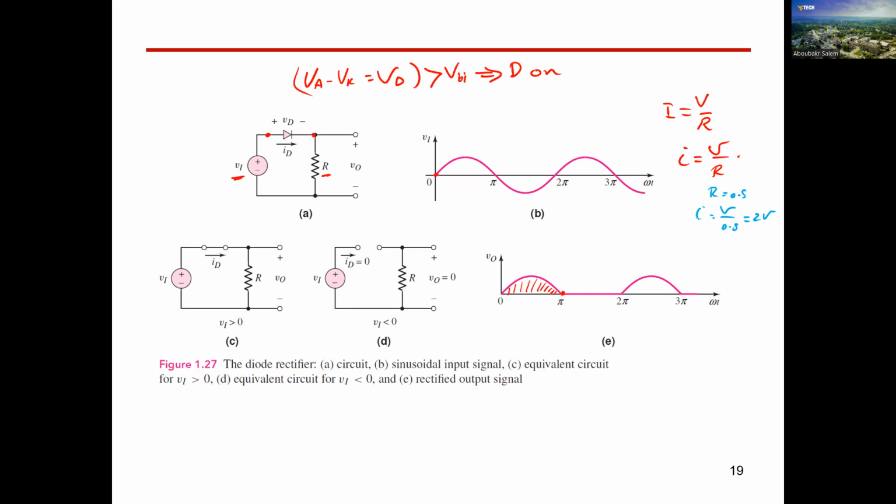So in this case, the current is going to be twice the voltage magnitude. If I would like to draw this current curve now, I expect the current to start here, increase, and then decrease at this point. Sorry, this is a freehand sketch. The current reaches 0 at angle pi, which means 180 degrees. So current drops to 0 at this instant. If you remember, in the previous slide, we mentioned that the condition to turn off a diode is that the current reaches 0. So once the current reaches 0 here, the diode will be turned off. Diode off means I equals 0.